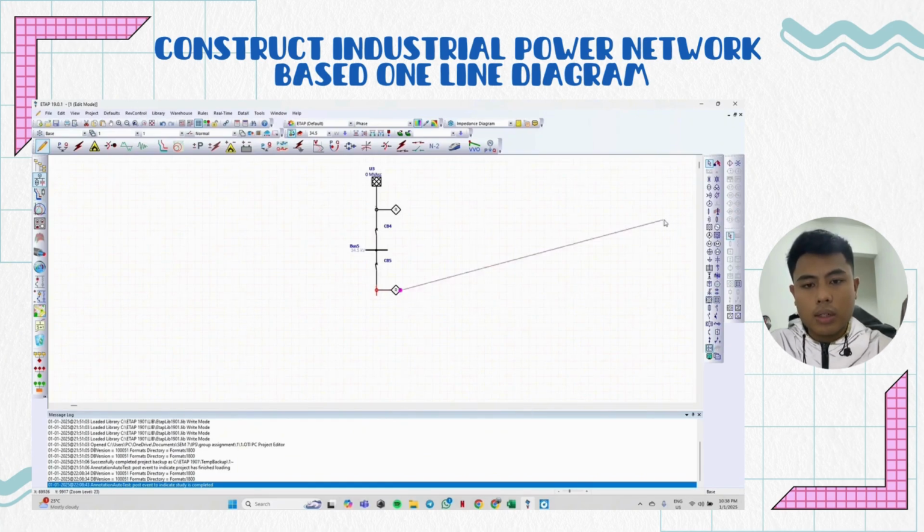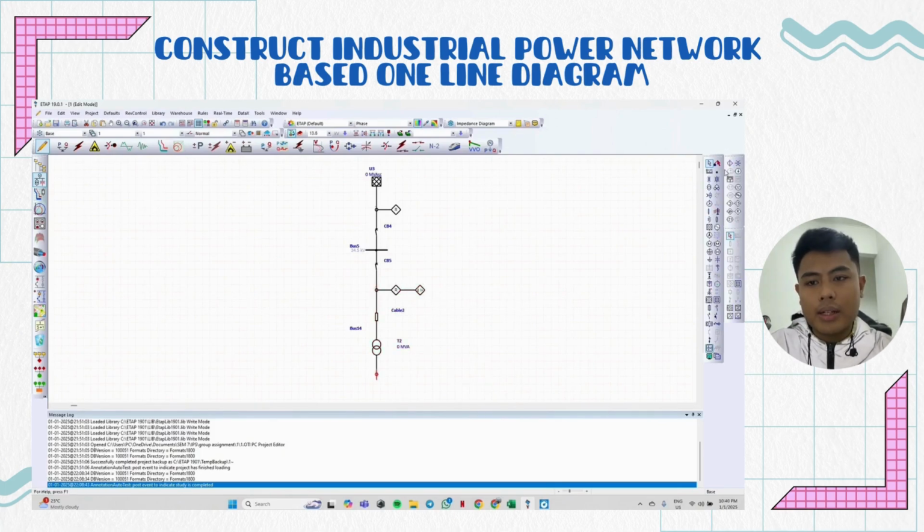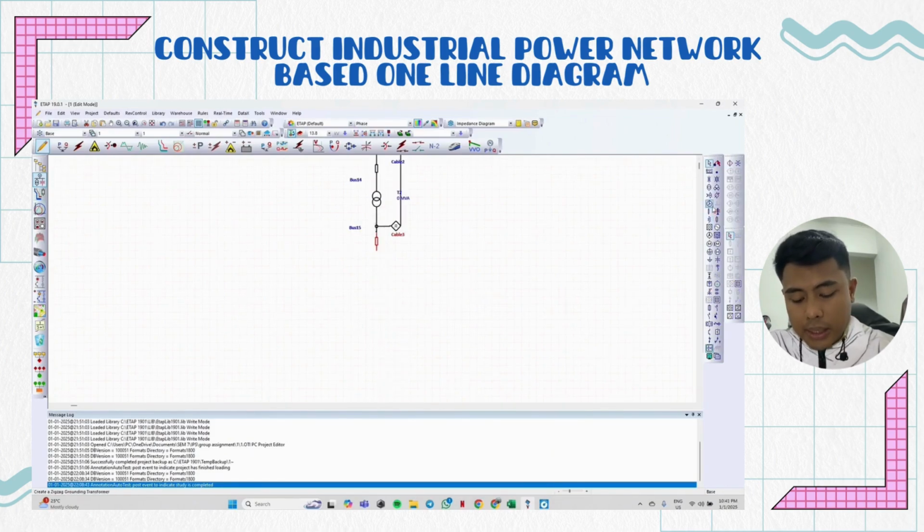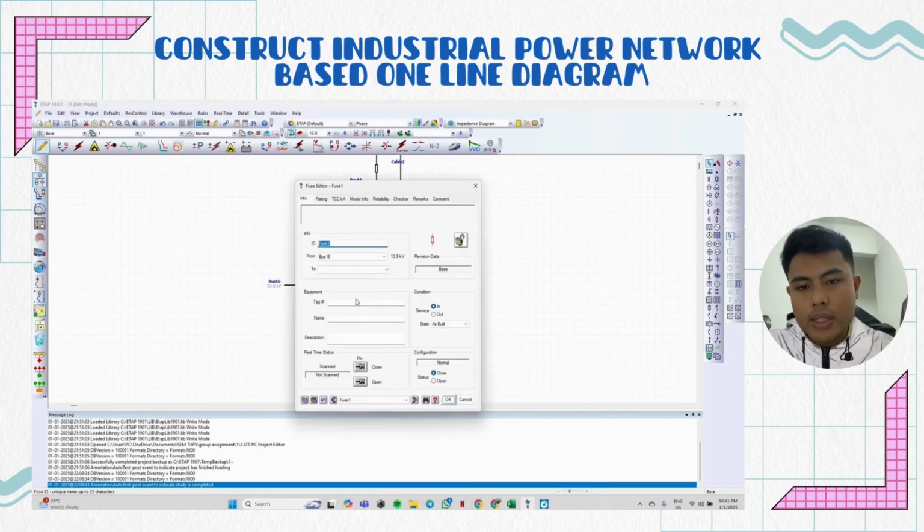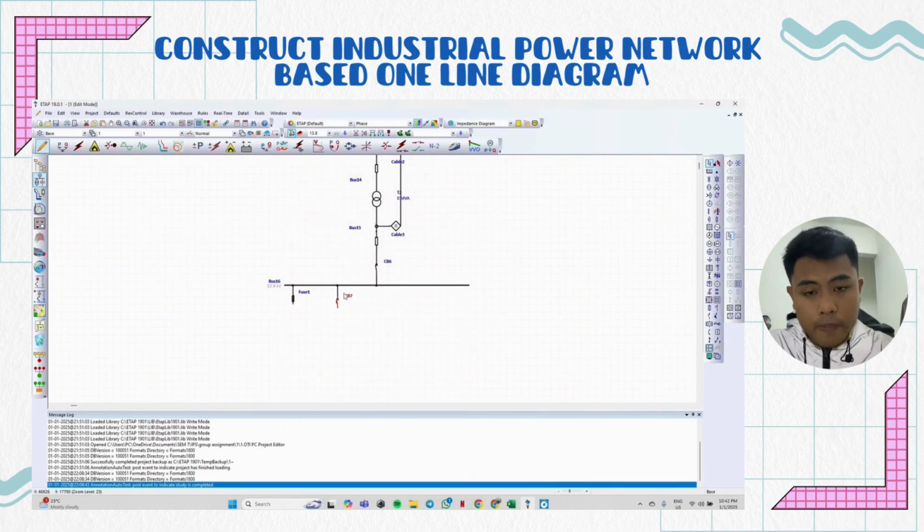For this video, I have cut some of the steps as they are repetitive, or to make it less time consuming. After we finish all the network in the utility bus, we go through to the switchgear bus, which has 4 bus bars. The first bus bar is fuse switchgear, and the other 3 are circuit breaker switchgear, which have induction motor load.